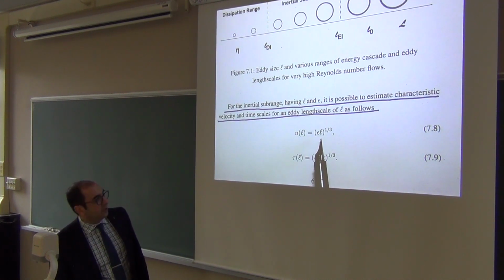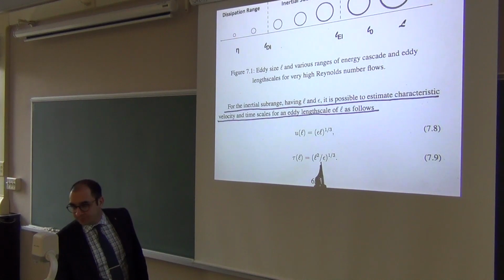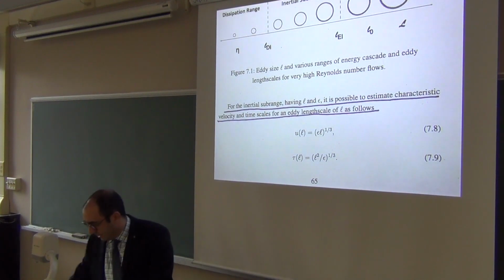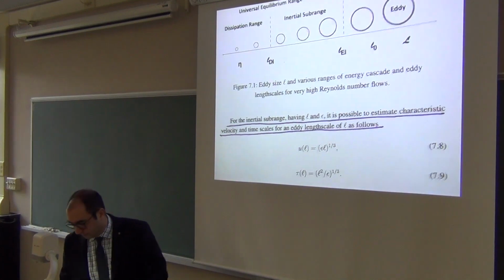Viscosity should not be here. So it is uniquely described by epsilon. And the time scale of fluctuations, again, is uniquely described by epsilon, the dissipation rate. Of course, L needs to be there because you have to tell me what length you want to look at, right? So really, it is only uniquely described as a function of epsilon, the dissipation rate. Really profound.